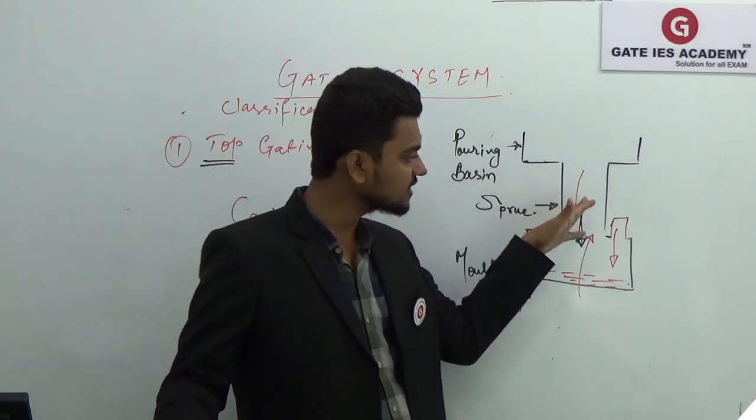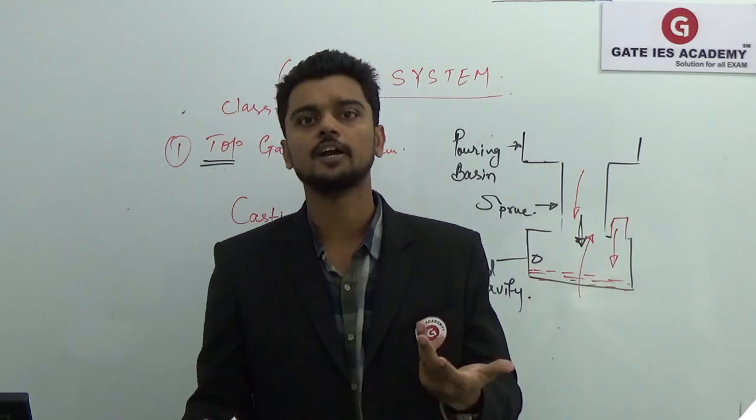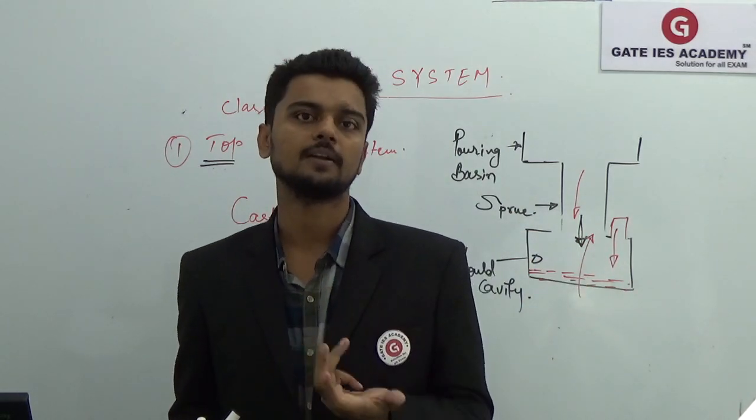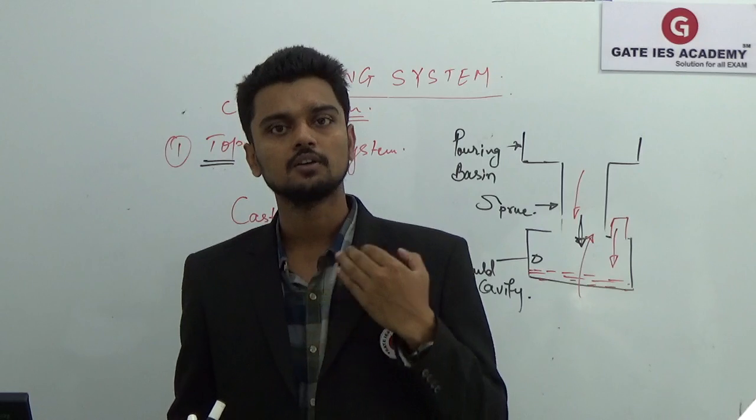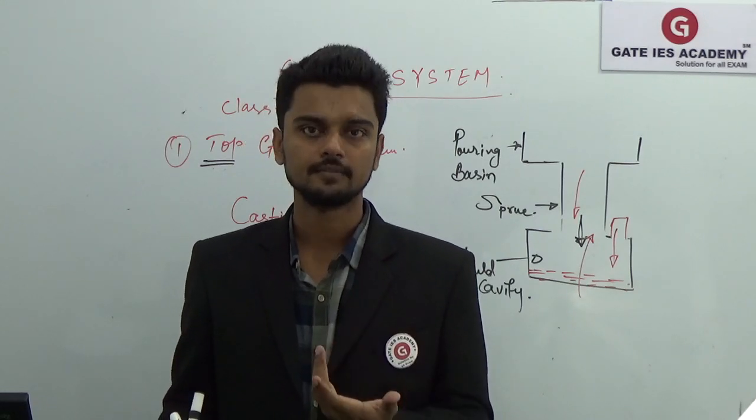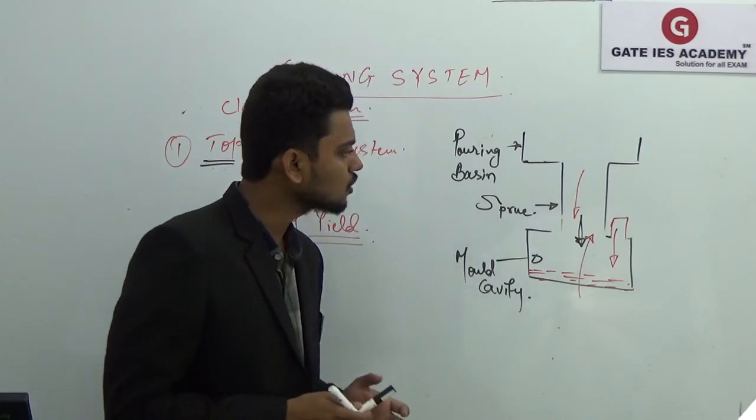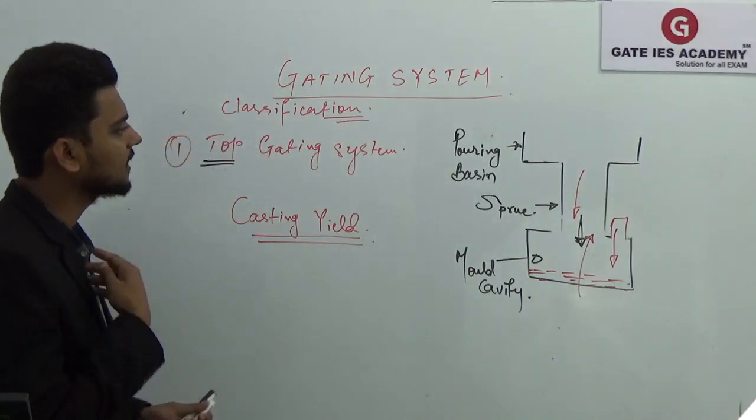So in this top gating system we are not using any runner and all that. So obviously we will not have extra molten metal that will solidify in your runner. Okay. So obviously it will give you the higher casting yield.